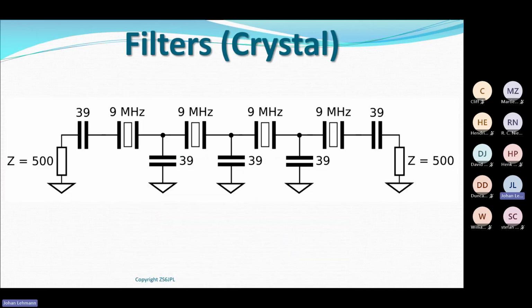Okay, next type of filter we're going to look at briefly tonight, because it's a very important part of a radio. When you get to modulation techniques with me around the middle of August, you'll see why we use a crystal filter. When I want to generate sideband signals, it's important for me to have crystal filters to separate my carrier and my other sideband out of my transmission. And a normal inductor capacitor filter is just not good enough. It doesn't reach home yet.